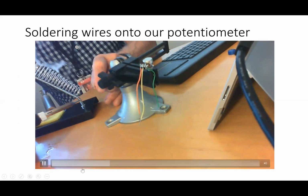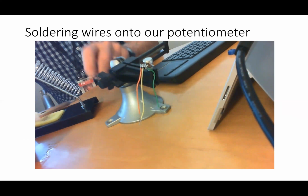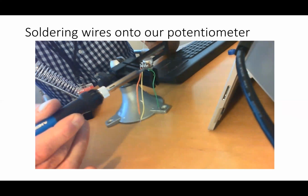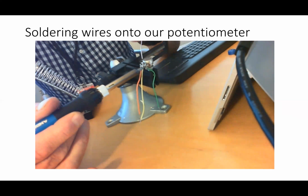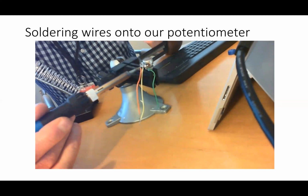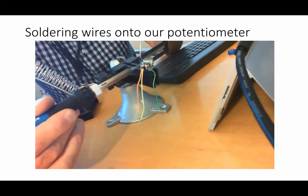There we are. And now we're going to solder the connections. Now, an important point is you do not use the soldering iron to carry solder to the joint you're going to make. You place the soldering iron on the two components to be welded together, which is the wire and the tab, and you leave it there until the two metal components are hot enough to melt the solder onto the joint. And you do this by dabbing the solder down onto it.